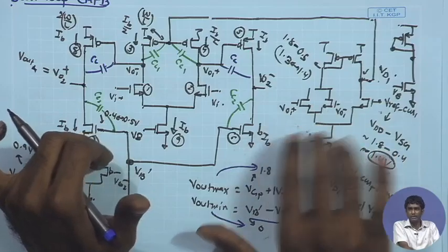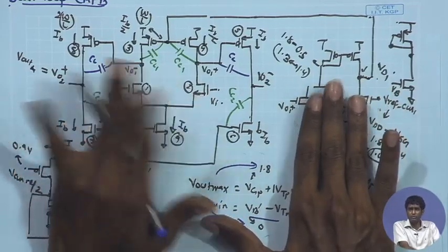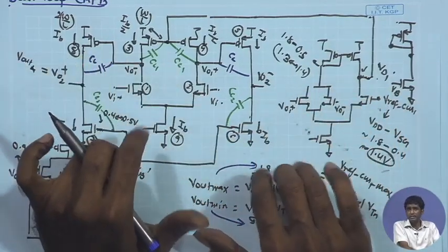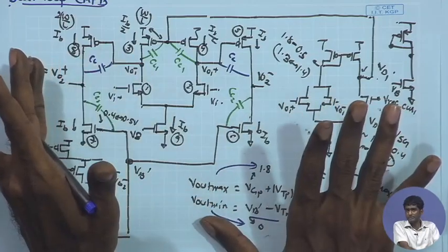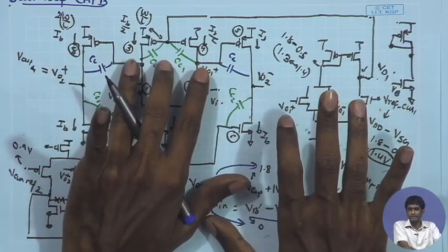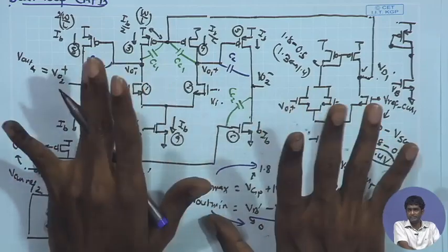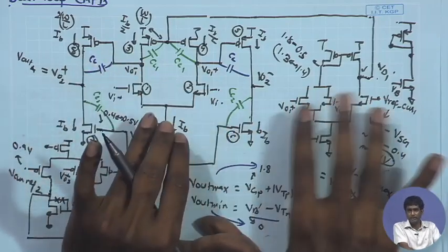In some applications you may need to keep the bandwidth of the common mode loop also similar to the differential case, in case you have significant common mode disturbances coming in and there is a chance of the output common modes of the first stage and second stage getting disturbed. In that case you may like to track it closely.